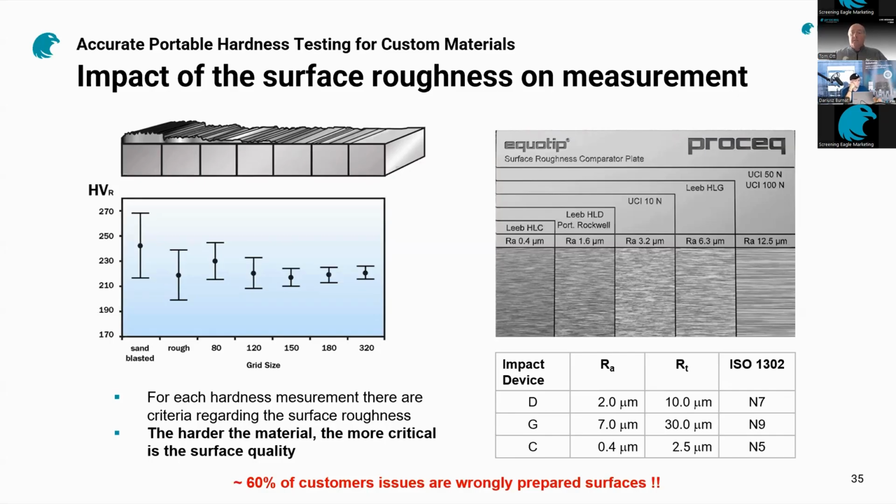Darius. Correct. Thanks for highlighting this. I want to add one thing. Users sometimes also use the ISO standard for the conversion, and you exactly nailed the point, Tom. Because, for example, the ISO standard and the ASTM standard for aluminum specifically use two different test forces, and those results do not match because of the reason you have described.